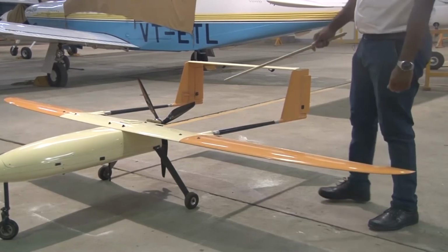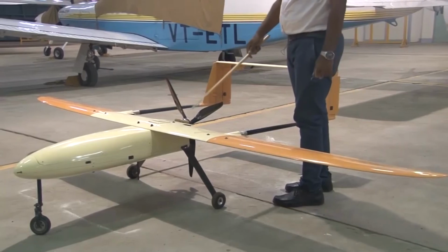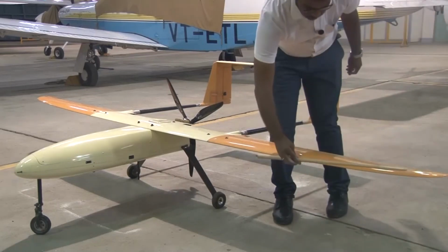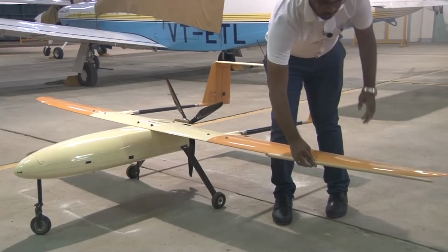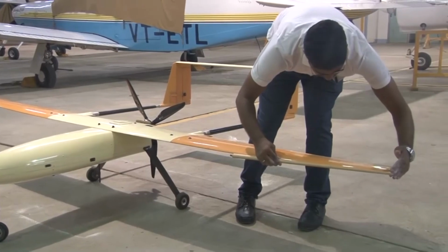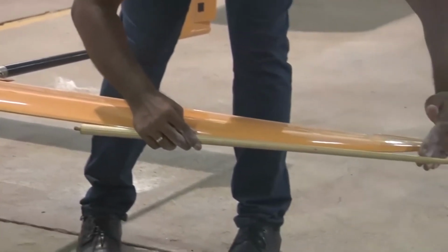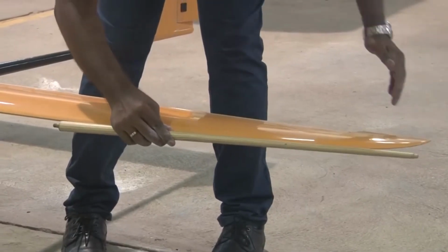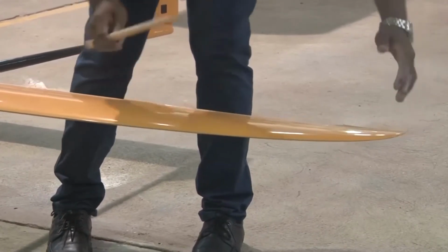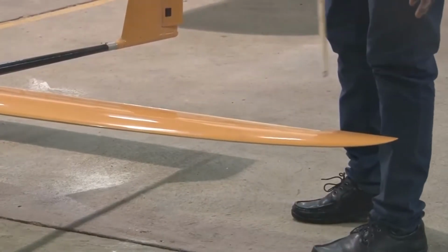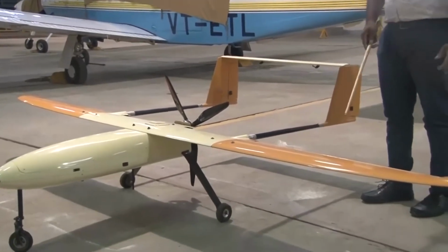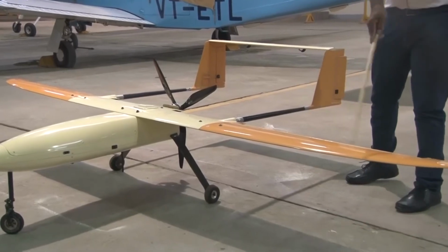To find the mean aerodynamic chord of this planform geometry, we need to adapt the methodology that we discussed in example 2. From this point, if you want to find the taper ratio of this section, you need to consider this portion as your tip chord, and you can find the corresponding values. So you have to find the mean aerodynamic chord by considering this as 3 sections: first a rectangular section, then a tapered, and then an elliptic planform.